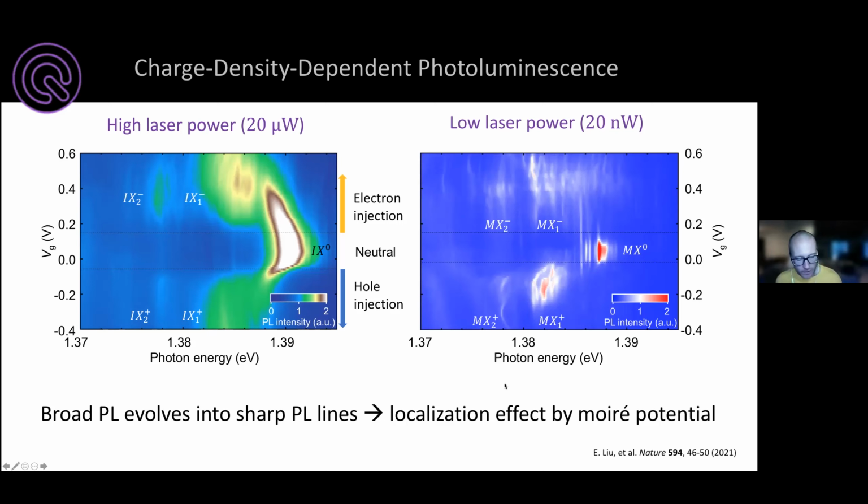The way that we do that is you can essentially measure the device and then go back afterwards and use things like second harmonic generation to look at the relative angle. But we do get high yield. We were able to measure up to now probably about 12 or 13 of these devices, the first set. And in the second set, the photocurrent measurements, we have 4 or 5 of the devices. So it's become routine, but I wouldn't say scalable.